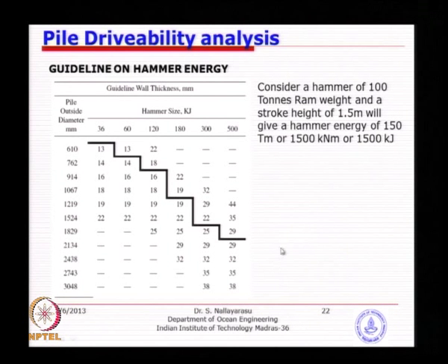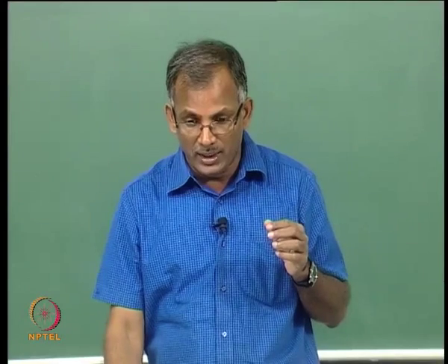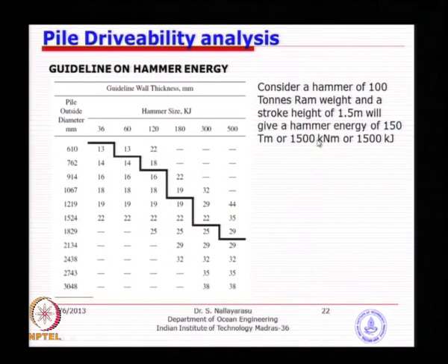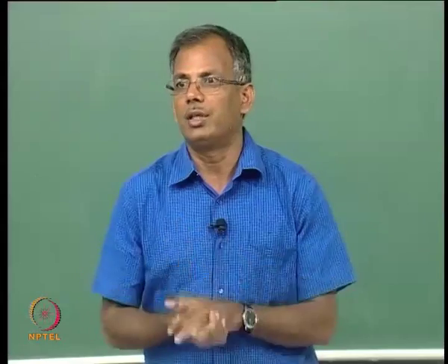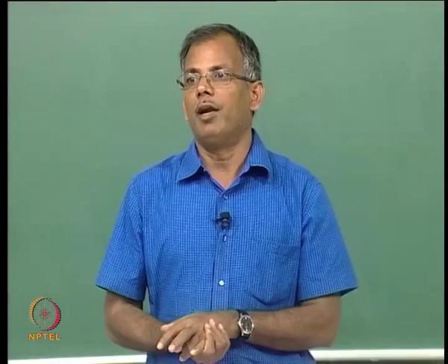If it is a 1500 hammer, it is definitely a very big size, which you do not want to put onto a pile of smaller size, as it will make the pile stresses very large for both reasons. One is the weight itself: as the energy of the hammer is larger, the ram size is larger, and the total weight of the hammer is going to be large. So static stresses will be very large.